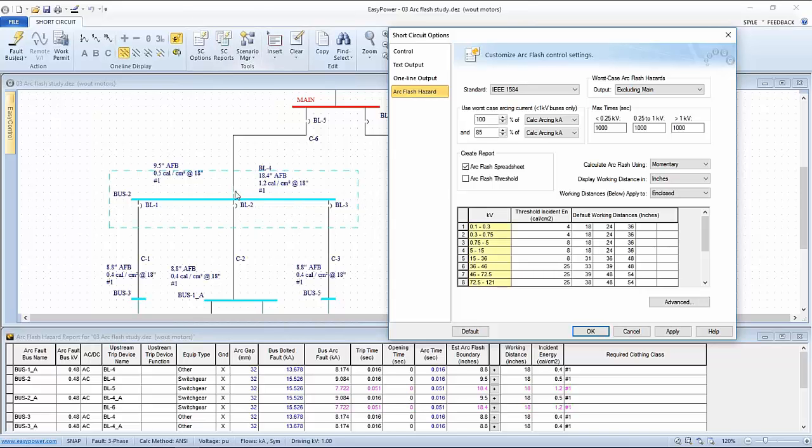And during data collection, if I observe that there's no barrier between the upside cable connectors into this breaker and the bus itself where I may be working, it was observed during IEEE testing that the plasma ball or the arc itself could travel, so an arc that forms upstream could actually bridge the breaker if the plasma ball were large enough. And so if there's no arc barrier between this connection point and the bus, then I cannot use the trip characteristics of this breaker. And that's what's being shown here.